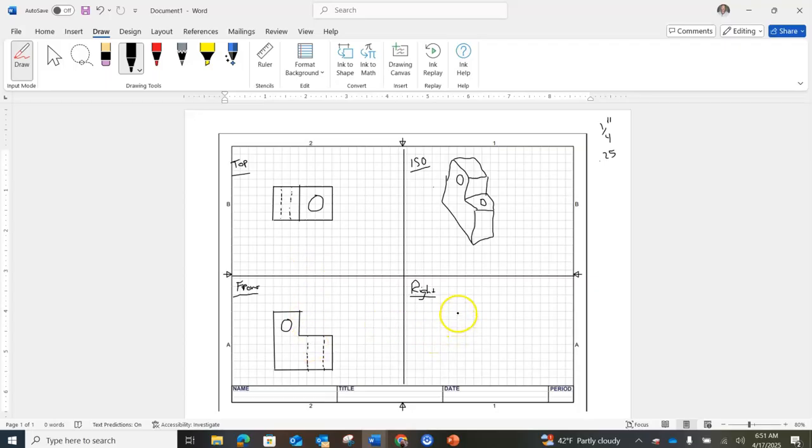Now for the right side, same type of deal. I'm going to draw that out like this. Ooh, there, I made it snap straight. And it's even from the bottom of the shape and the top of the shape, the same height. Now this is where some people get a little confused, but it's got to match the depth. Right here, 4 squares is what I'm using, or if at a 1/4 inch, I would say it's exactly 1 inch. More on that in dimensioning video coming up. But this is 4 squares deep. That matches this one here.